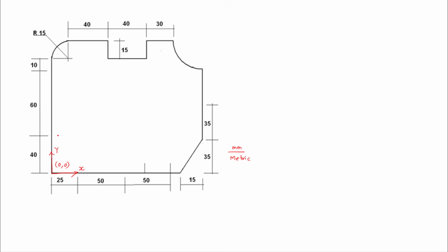Now when we carry out the contour finishing programming operation, the controller has made our life very easy. We have to just program the points of the contour. We have to give the information about the points along the contours and the required interpolation function, and the controller will automatically compute the cutter location point. So we are providing the contour points that will be converted into cutter location points. But to consider the cutter location point, we have to add the diameter of the tool.